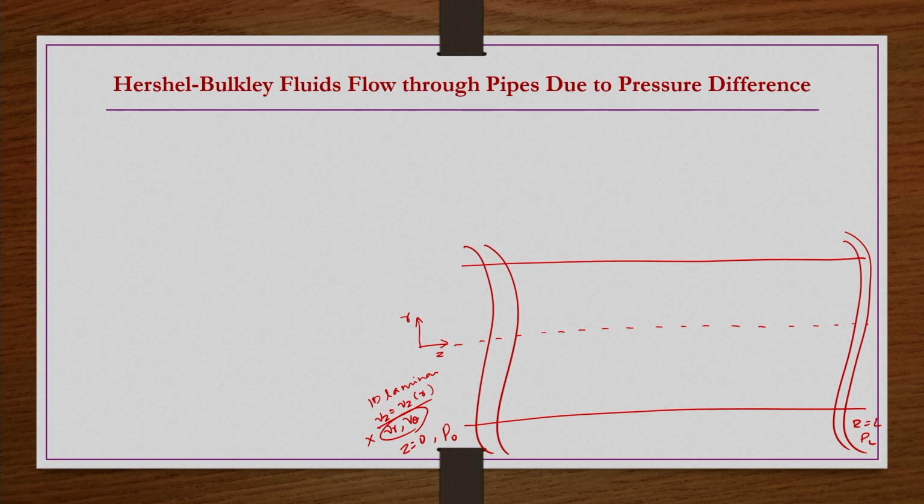Now, as long as the geometry is the pipe geometry, and if you take 1D laminar motion, then what we have seen in the last few classes is that the shear stress tau Rz is nothing but minus delta P by L times R by 2, and this is irrespective of the nature of the fluid. However, we are going to derive it once again in this class, in order to have a kind of continuity.